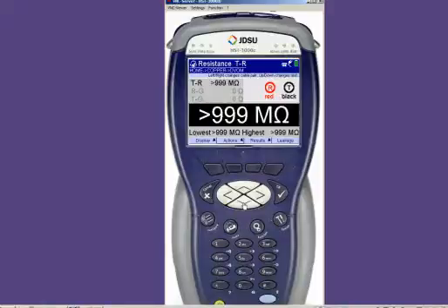Well, from our side of the business, not that you folks care at all, you can't afford to have the box with the lowest number. So we're all sitting at greater than 999. Crazy high in my opinion. As a cable maintenance person, I never took 20 megaohm of trouble off of anything and had it make a difference, right? It's just too high of resistance.